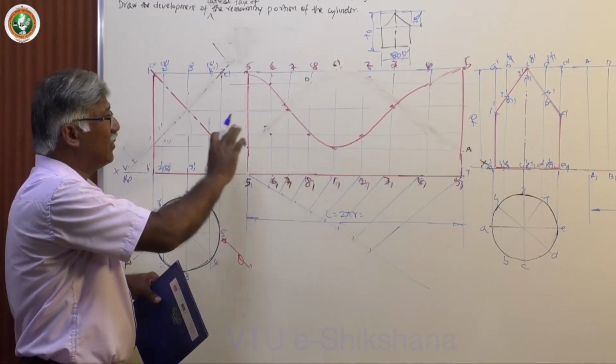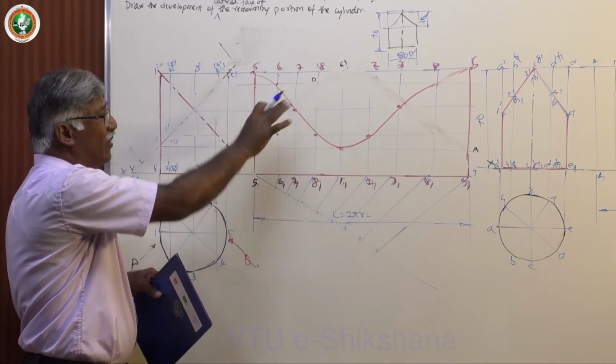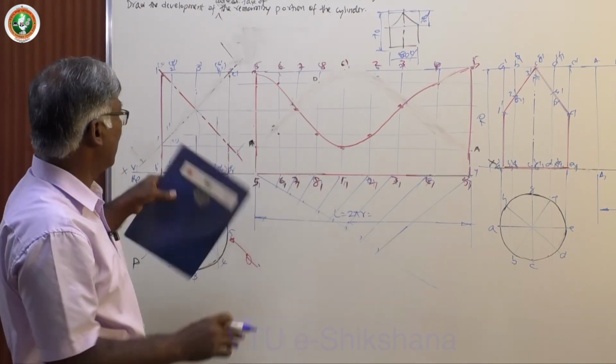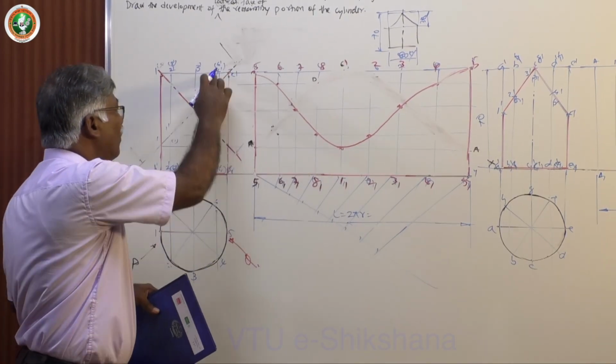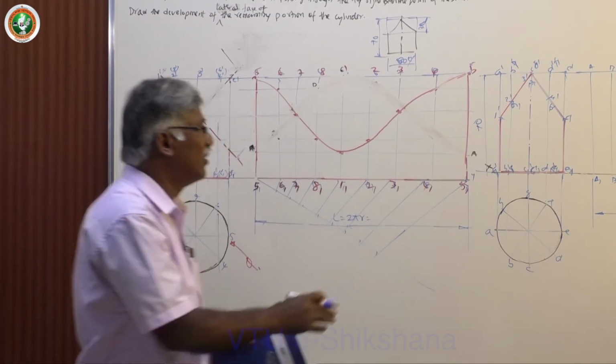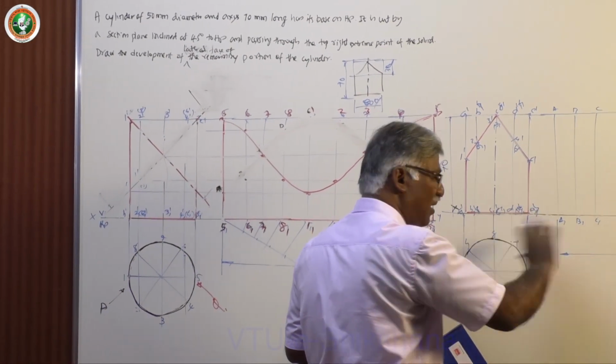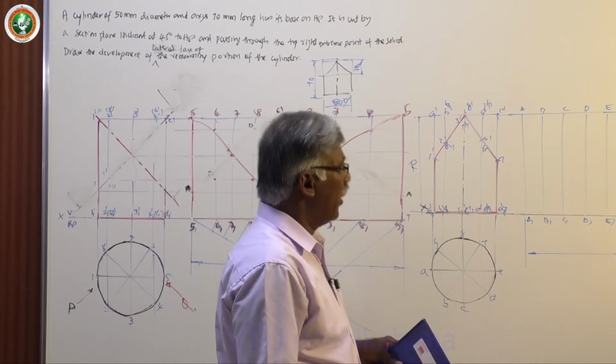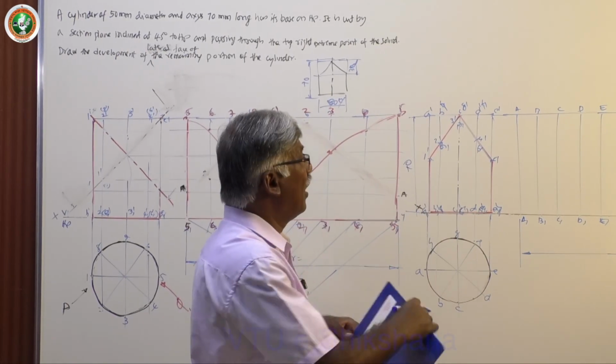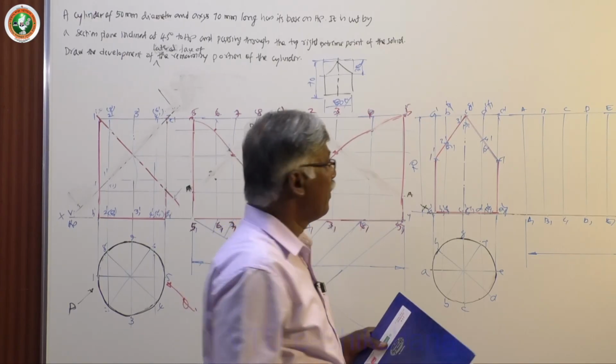But suppose that if you don't project, you never feel like parallel line method you have taken. Height is exactly equal to the height of the cylinder. So you must project. You should not keep any gap between this figure and this. XY line, let it be there. Continue it now. Now start working this particular problem.